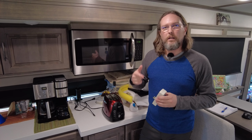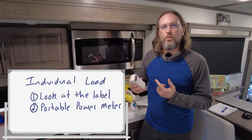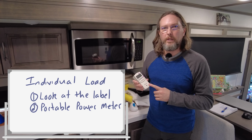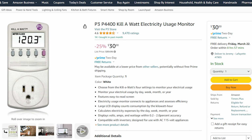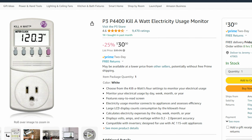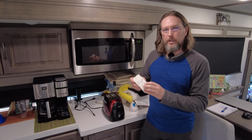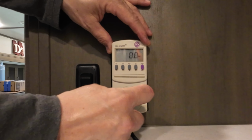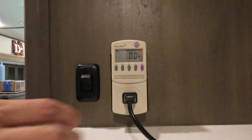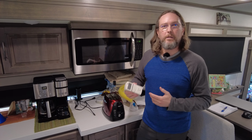So the second method within this individual load technique is to use one of these small portable watt meters. Now, this is one of the more popular kind. It's a kilowatt meter, and you can find these on Amazon for about 30 bucks. The way that these work is you simply plug this into a 120 volt outlet in your RV, and then all you have to do is plug your appliance into this, and this kilowatt meter will show you exactly how much power that item is drawing.